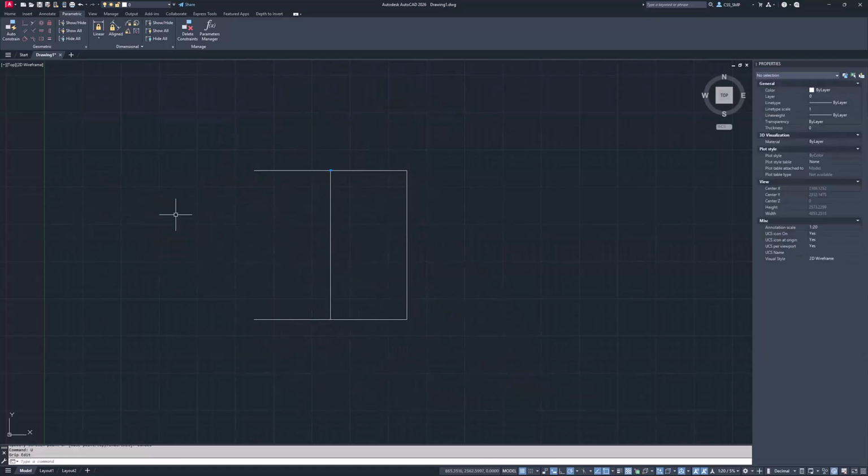I'll just undo that, get rid of that one. You will also notice that when I selected the objects, when I selected this one here, and then this second one, the second object moves. So just be aware that when you're creating your constraints, the sequence that you select is important.